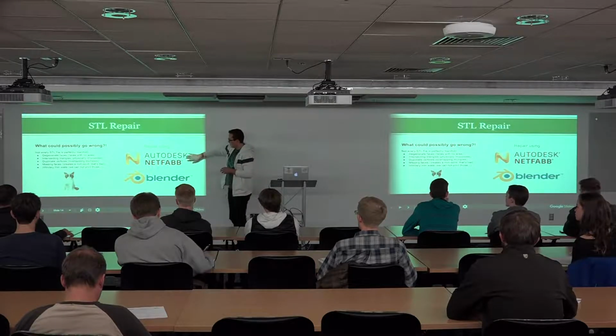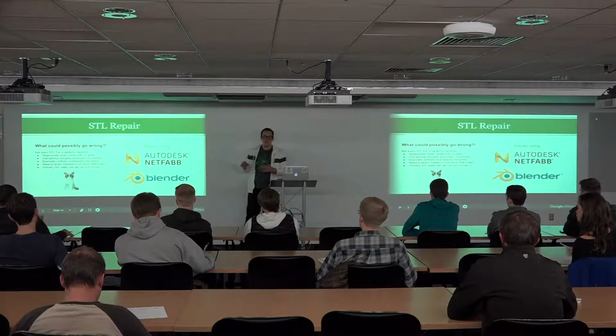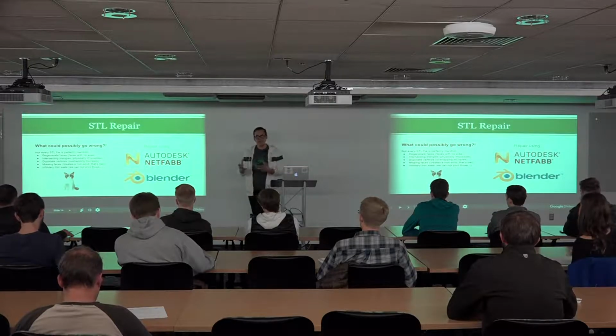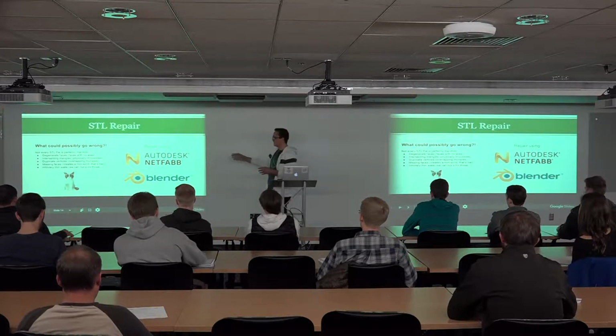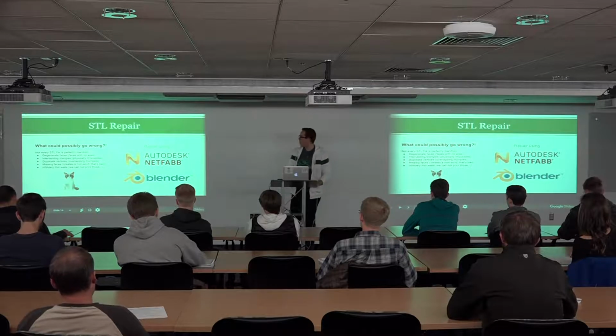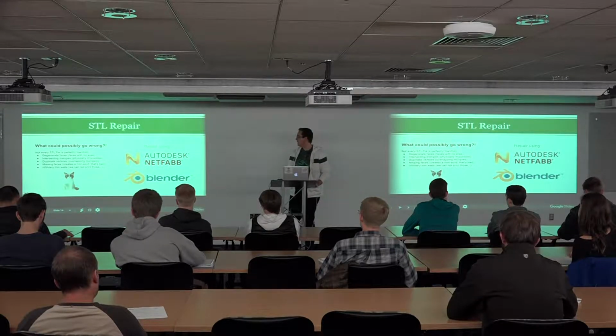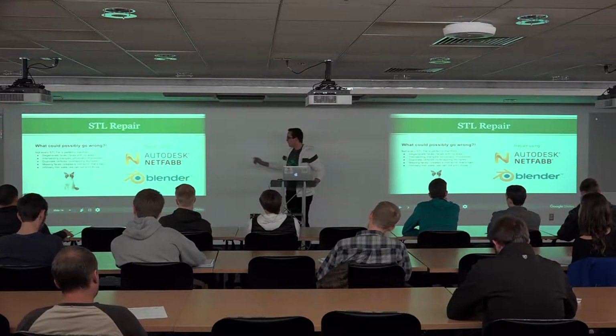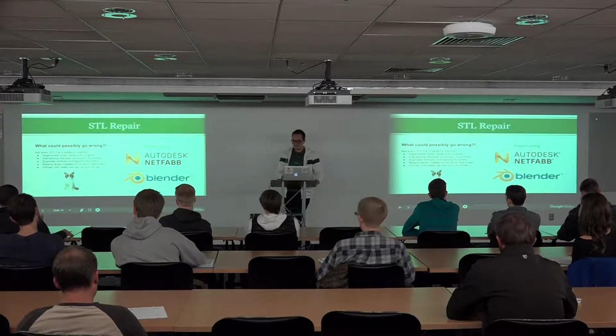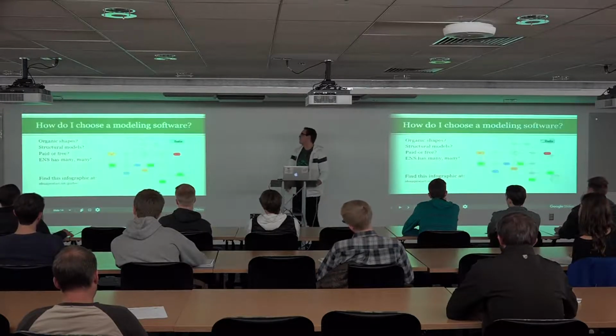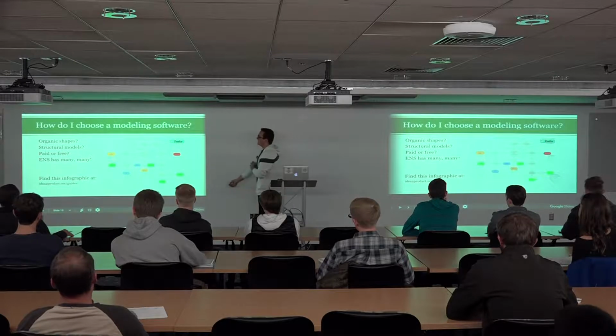So we've got NetFab for doing automatic repairs, and any of our staff can help you do that. If you go to slice your model and it doesn't look quite right, talk to one of our staff and we'll help you NetFab through it and hopefully fix the issues. Otherwise, you can go to a more in-depth repair in Blender, which is an adventure in itself.